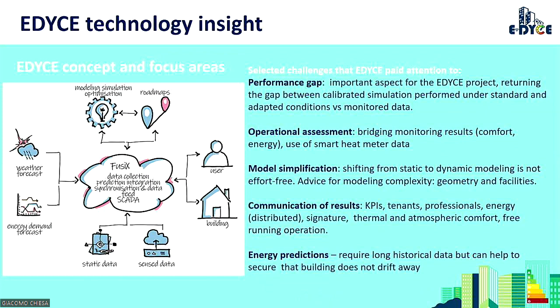The last challenge that we covered was about energy prediction. Here we made some interesting progress towards seeing, if we have historical data of the building, so from the operational data, how we can predict the next days, weeks, or months of the operation of the building. This is especially interesting if you would like to monitor a building drifting away from its historical operation.